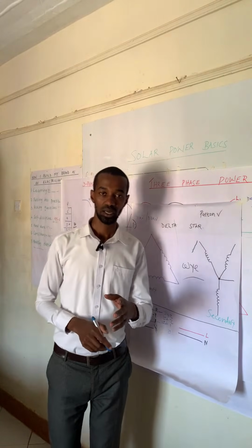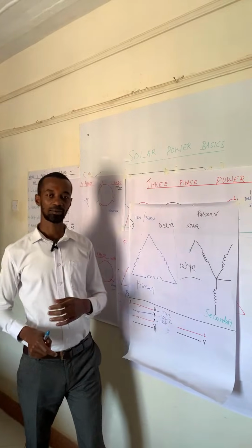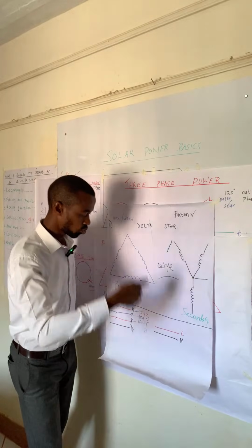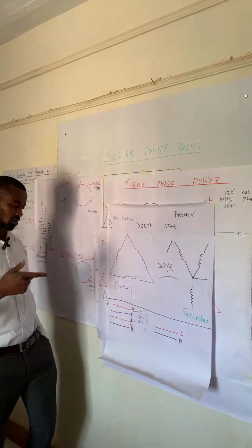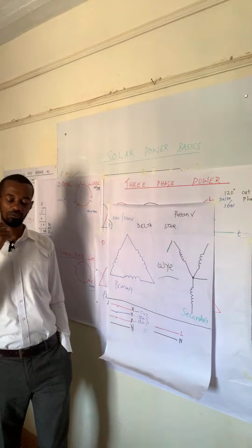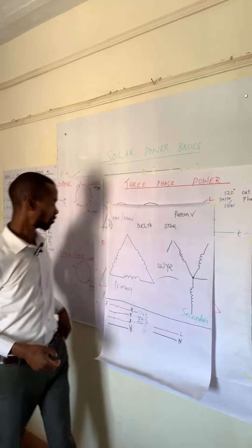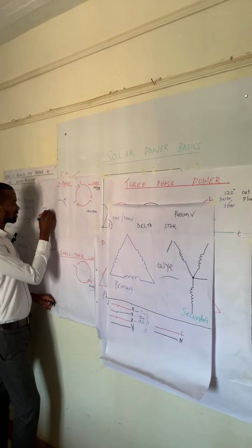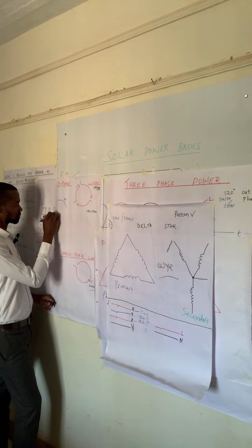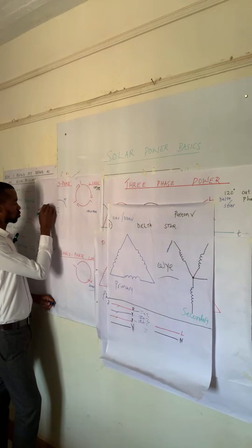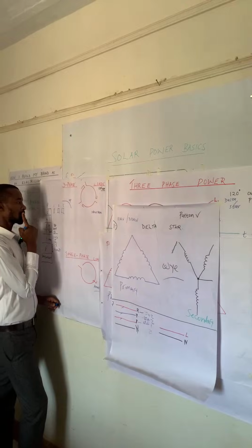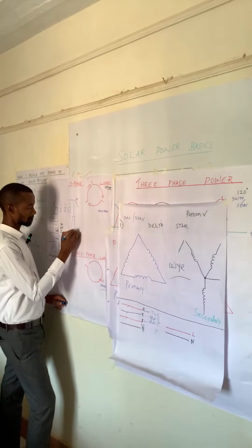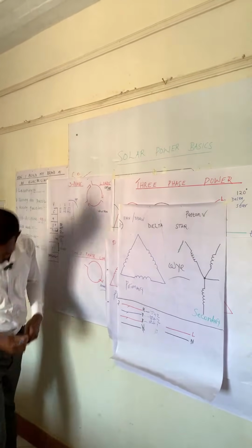Another downside to not balancing the loads is that any protective device that is connected to that load before it is supplied to energy meters will start to arc or to overheat. Let's take an example of a cutout. For these residential areas, you find that in this distribution board there are three cutouts, 1, 2, 3, and then the neutral goes direct to what we refer to as a neutral bus bar.